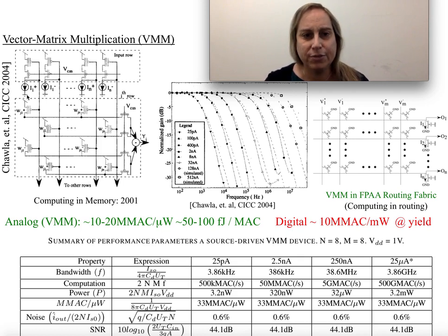Now I can do this in this form. There's many different architectural forms. This one actually is playing off the gate voltages and current mirrors. Another way to do it would be to actually play off the source voltages and look at the summation you have in such a network. Works really, really well. Why would I pick this?